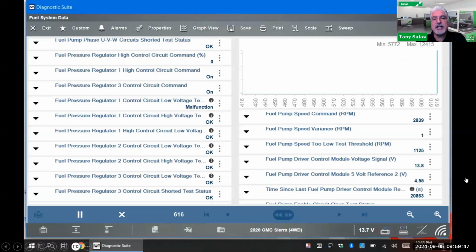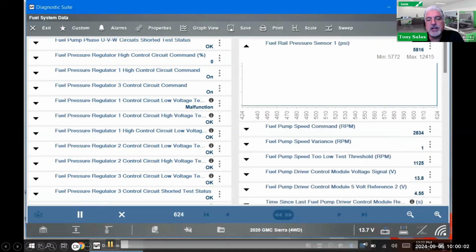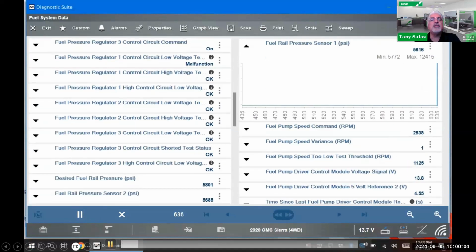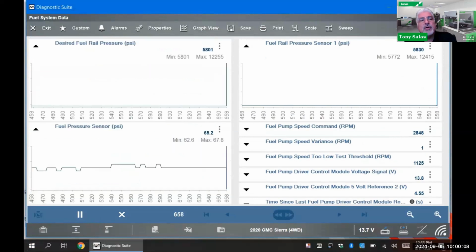So again, we've got to get up to speed. Here we can see an LM2, and I did this one with my Zeus scan tool. And once again, there are our OK signals right there on the regulator. Similar readings, different trucks, obviously both GMs. But what I'm trying to show here, and I've shown this before, is the ability to graph and compare one reading with the other.